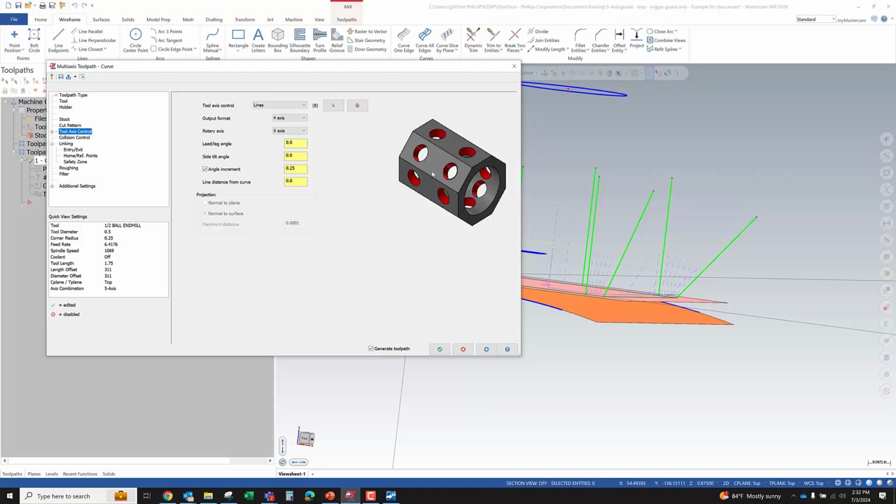license, we can drive a toolpath that is offset from the center line of the rotary with vectors, provided we only have vector rotation along one axis. So if you had a rotary 4th axis A on a Haas machine and you had some feature that was offset that had a tilted wall, as long as it only tilts perpendicular to the axis of rotation, you can limit the output to 4 axes. What else do we have in the toolpath? Well, some kind of cool features.